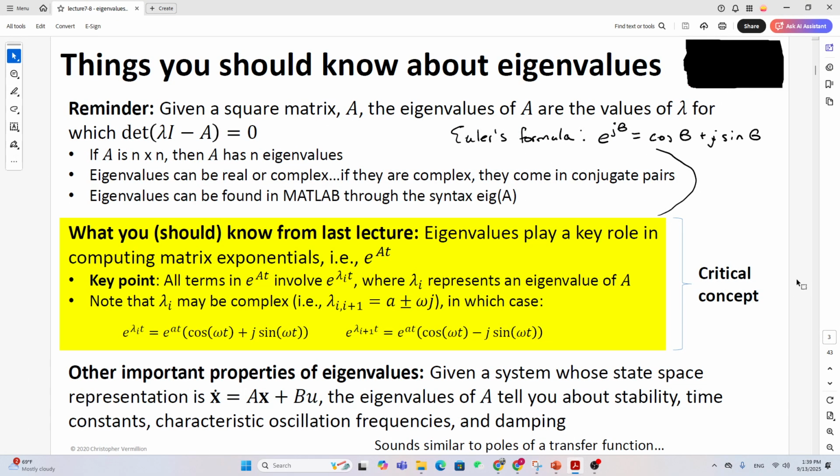So as for eigenvalues, we all know that any control system can be expressed as x dot equals Ax plus Bu. And the A matrix, which is a square matrix, tells us the eigenvalue information of the entire system. So if you do lambda I, where I is the identity matrix and lambda is your eigenvalue, subtract A, and take the determinant, this is how you derive your eigenvalues from your A matrix. And in MATLAB, there is also a very simple way, using the syntax eig(A), so that you can get the eigenvalues of your system.